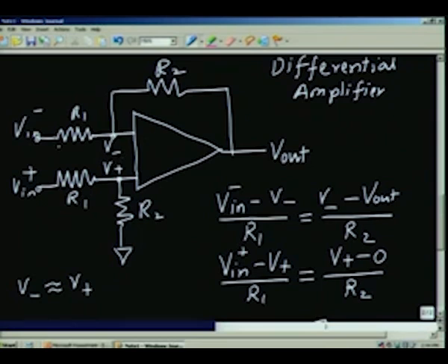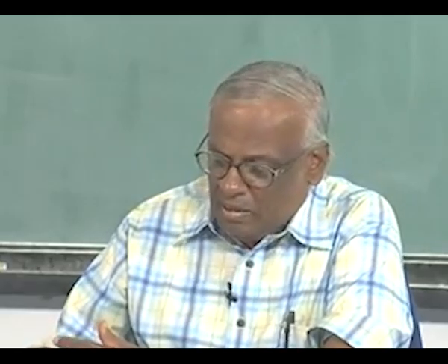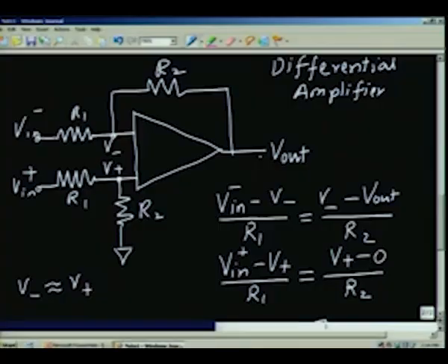That means it does not take any current from the sensor, but the output can give you sufficient current for driving some external circuit. So, sometimes we can simply have a unity gain amplifier which will give you a capability for supplying larger current, but without loading the input or the sensor itself.